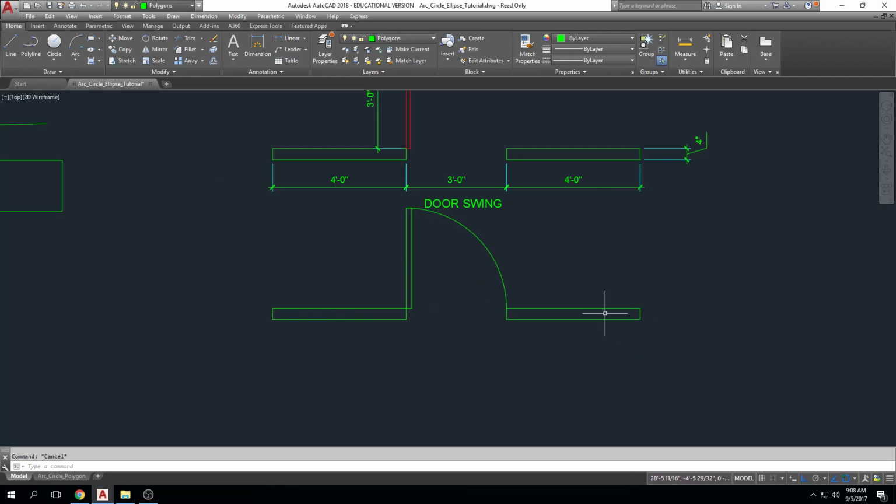All right, so that's a lot in an hour, right? Lines and arcs and circles and rectangles. So you have some tools to draw now, okay? You can measure whatever you've drawn to make sure that it's correct. You can select and delete things if they're not correct, and you can redraw them, okay? Don't be afraid to use extra geometry to draw geometry, right? So if I have to draw a line across here to create a gap, I can do that, and I can delete it when I'm done, right?